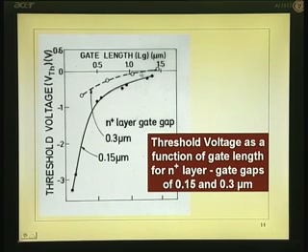Okay. There you get threshold voltage of about 0, or slightly more than 0, close to 0. But you keep on reducing the gate length. In other words, you are reducing the channel length itself, you get reduction in the electric field. The threshold voltage shifts negatively.